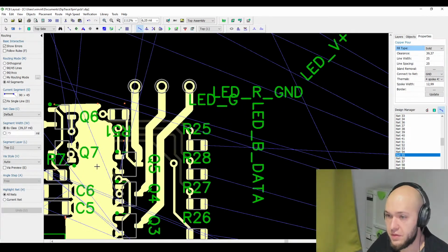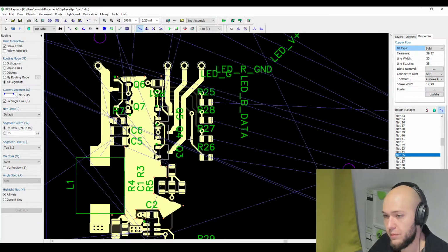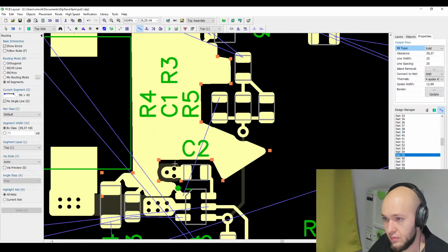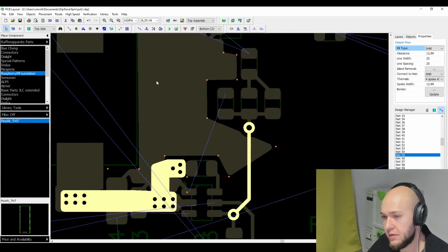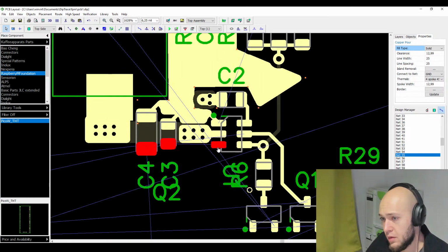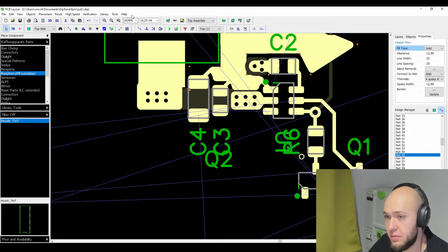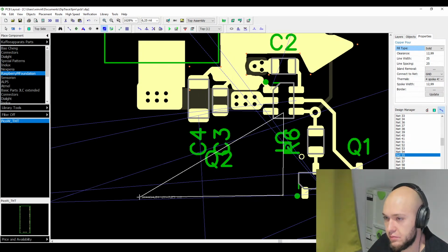And these aren't high power wires at all. So, with this added, we can almost start. Next we will need to add some positive voltage plane. It needs to be a plane because we need to get heat out of the device. And for that we will simply start adding a big plane right here.